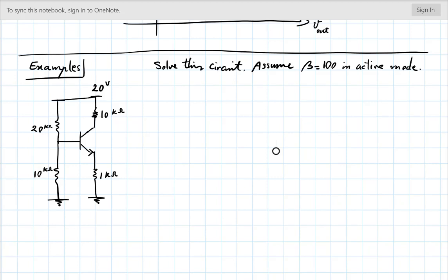If I disconnected this wire there, now those two resistors are in series, right? What would the voltage be at this node? Yeah, so 6.6 volts approximately, right? Let's say 6.66 volts. You have a simple voltage division there, right? Of course, things are not that simple because you have this connection, which means you have this base current, which ruins this whole thing, you might say.